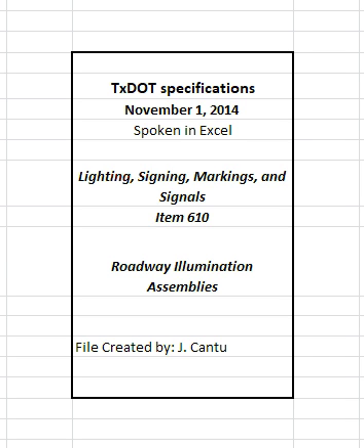Replace conductors. Unless otherwise shown on the plans, remove abandoned concrete foundations and replace surfacing in accordance with Section 610.3.3, Removal. Do not remove existing concrete bridge lighting brackets. Furnish and install new internal conductors, fused and unfused connectors, and lamps. Furnish and install new transformer bases that meet TxDOT and plan requirements when relocating transformer base poles. Destroy existing transformer bases to prevent reuse. Accept ownership of unsalvageable materials and dispose of in accordance with federal, state, and local regulations.